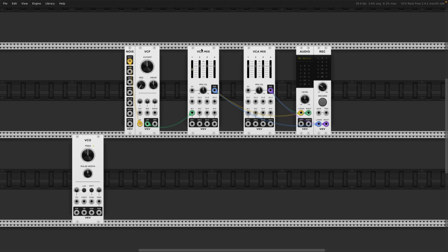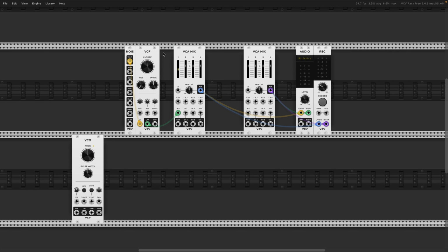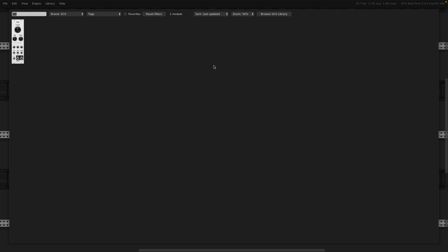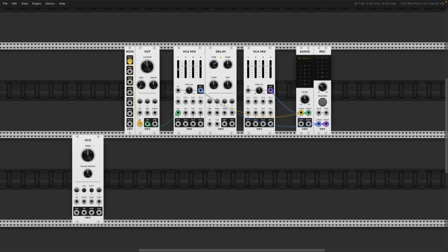And now, to get stereo sound, what we need is we have to shift the time of this. We have to delay the audio signal a little bit. So for that, we need a delay module. So we add this delay, and we'll feed the low-pass filter, the same output, into the delay first, and then its output, let's pick the mix output, into this mixer, but not the CV input, rather the in 1 input.